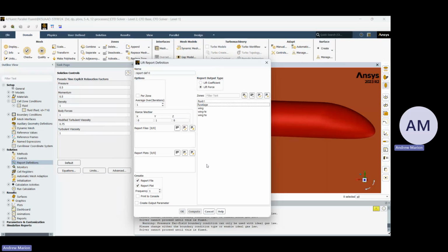Lift can be defined differently in different books. Some of them say lift only acts in the y direction, and this is what I agree with. If you have 10 degrees, the lift doesn't act along that angle. Most of the time, that's called normal force. Sometimes you see that also called lift, but traditionally, I think lift is in the y direction, so usually you can keep it as one. Then there's normal force and axial force, which act in the axis the aircraft is oriented in. So if you have it at 20 degrees, then that force will act in that 20-degree axis.